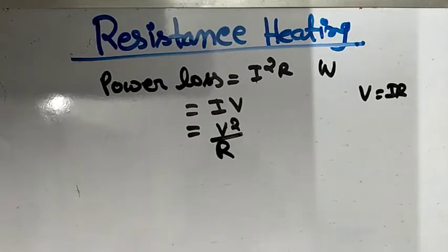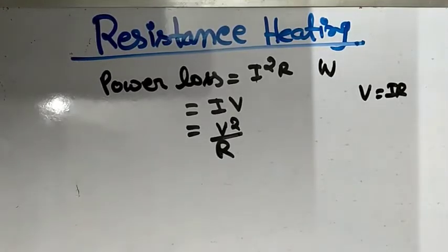And in high frequency heating, there is loss of energy at two stages. First, while converting power frequency supply to high frequency supply, and second, while transferring high frequency power to the heating load. Thus, overall efficiency of resistance heating is high, and this makes resistance heating competitive with other methods of heating employing fuels. In addition, the resistance heating method is favored on account of uniform power demand, giving a good load factor and almost unity power factor.